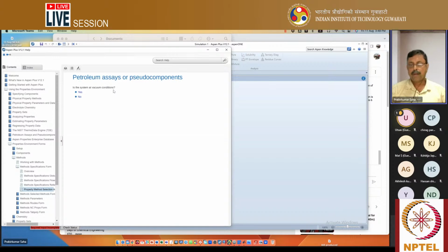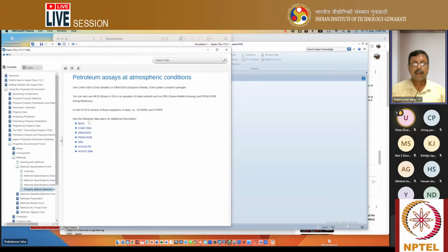I don't know whether you are working in vacuum condition. If it is not, you can say no. And these are the methods that are available to you. One of them is Peng-Robinson. So if you do not know which one to use, you have to take the help of this method assistant. I think I have told you these things. Okay.